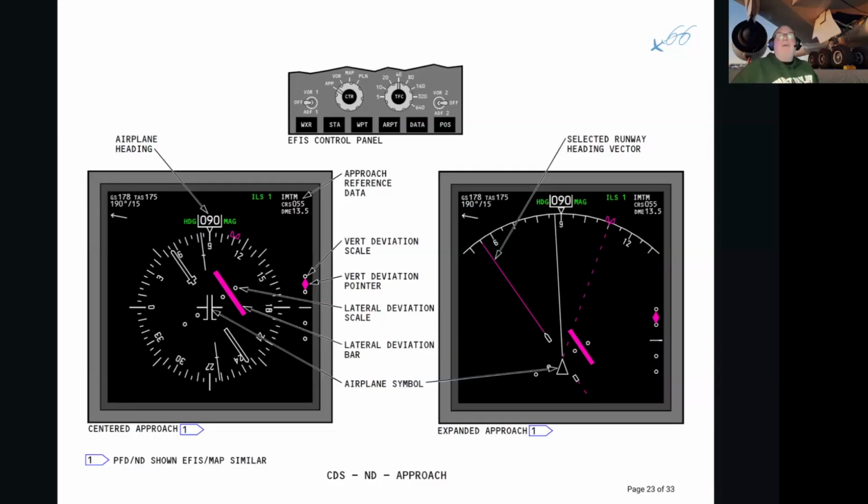And so we can have two different options from the EFIS control panel. So we talked about these outboard of the autopilot. The co-pilot's got one for his controls, for his navigation display. The captain has one for his navigation display, and you can have either the compass card, the rose, which we call the HSI view, or a centered approach, where you have the aircraft. This is God's eye view. This is God looking above, looking at the aeroplane and what it's doing. This is the one